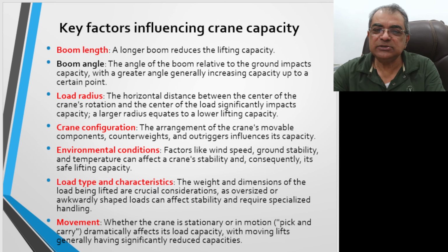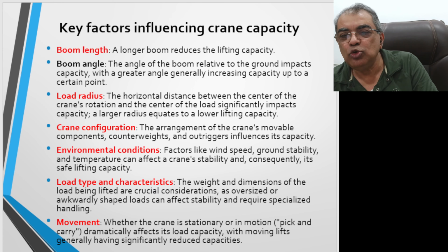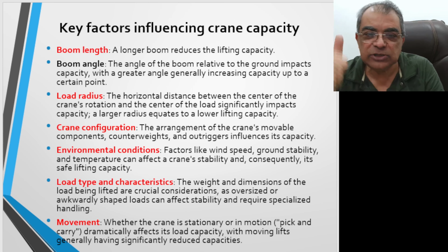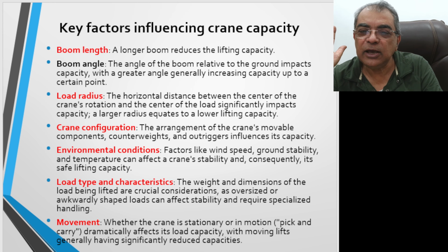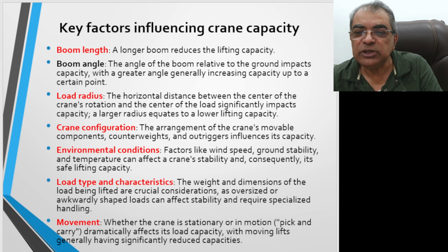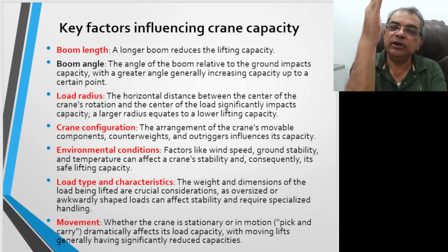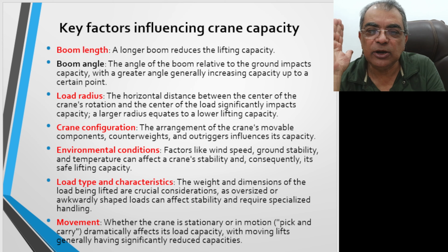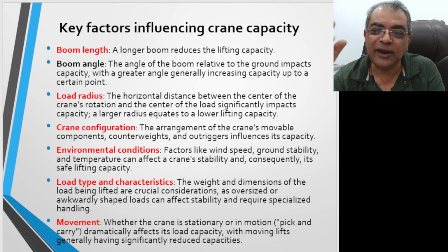So now to summarize, the key factors. What are the factors? Boom length: a longer boom reduces the lifting capacity. This is the thumb rule. Boom angle: the angle of the boom relative to the ground impacts capacity, with a greater angle generally increasing the capacity up to a certain point. Up to a certain point, you cannot put it at 90 degrees.